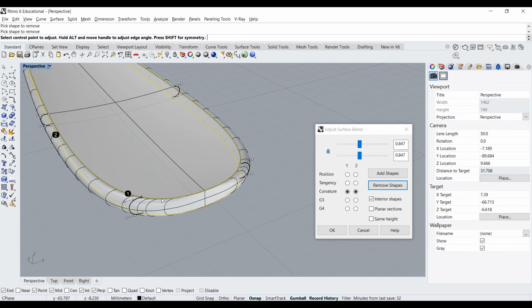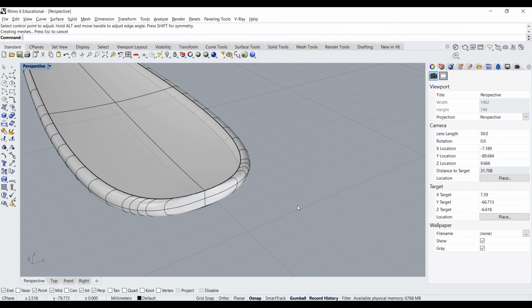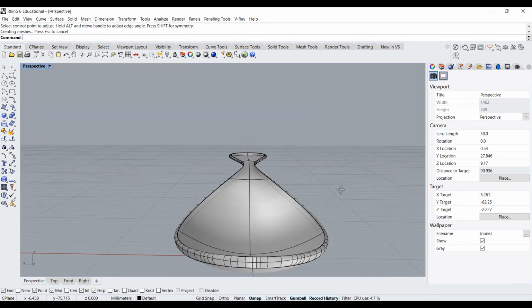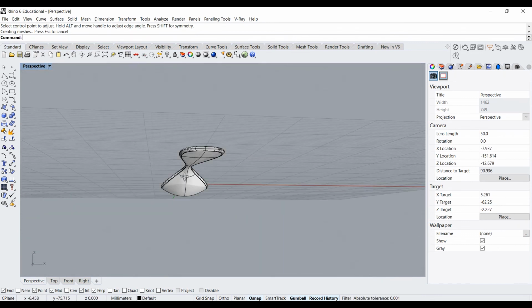If you did want it to be round all the way around, we might need to do this blend without auto chain and then join the two together, but just make sure you have the same settings. Or there's other alternative ways of using a curve and sweeping around two rails to get a much better blend. But for now, that's going to be fine for my design. So I click OK, and you see we now have a surface that wraps all the way around the edge.